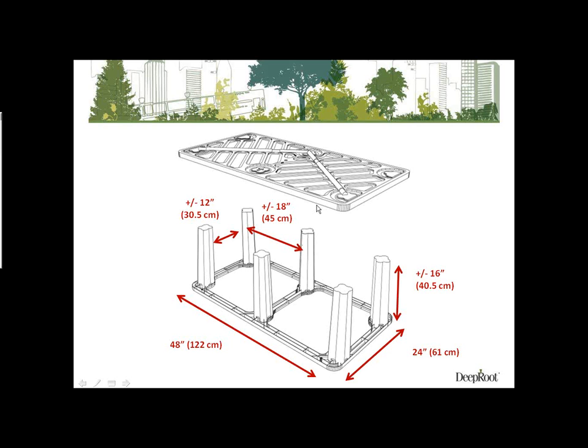Also, because the deck section only goes on the top layer of Silva Cells, the top is open, and the legs can be rotated underneath existing utilities, so that even ones that are buried on both ends can be added to the system.